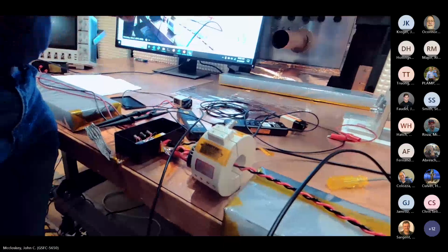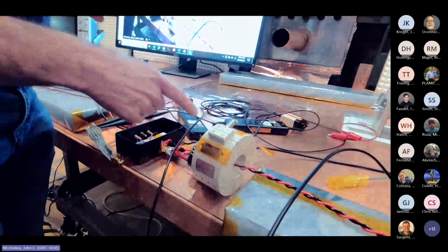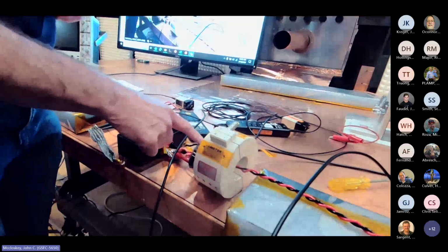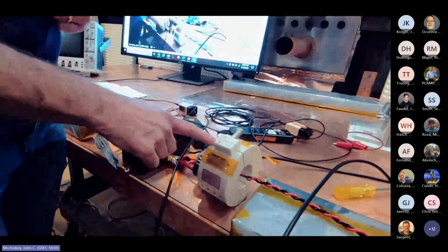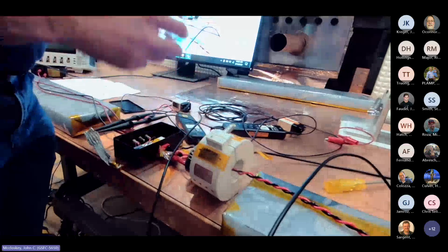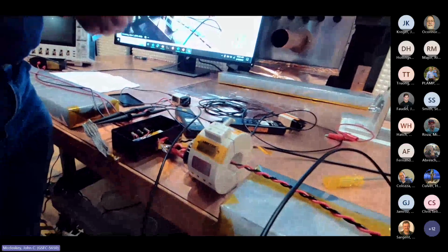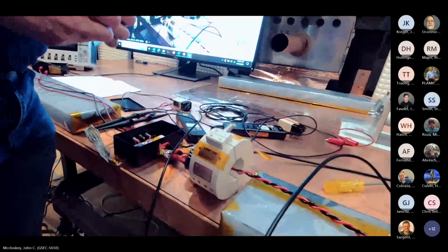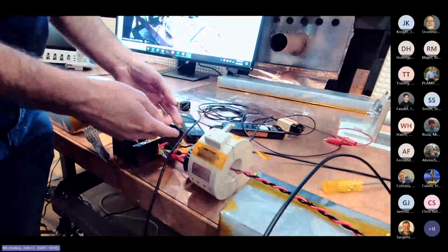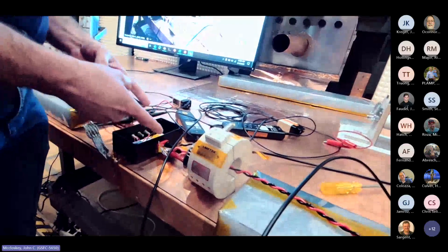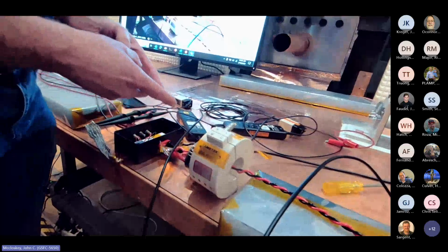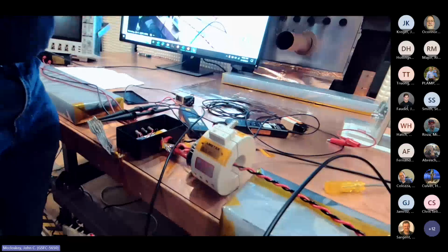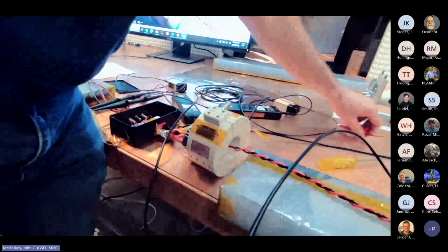So, I always emphasize, do hook up a current probe and make sure that you're actually seeing something injected, but you're going more with your pre-calibrated levels. The pre-calibration step is absolutely crucial. Do not bypass that. That's how you know what you're injecting. And then when you hook up a current probe, or if you're able to monitor voltage, which we are going to do here, then you can at least get some indication that you are indeed injecting something.